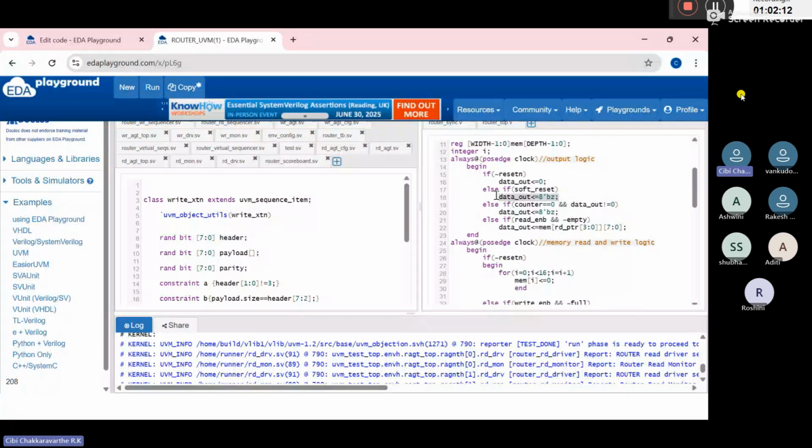If we are sending a packet to the destination and for a particular period of time there is no response from the destination side, for example, in some cases it is 30 clock cycles, then for around 30 clock cycles, if there is no response from the destination side, it will automatically do the soft reset. Soft reset in the sense it will not make the data 0. Instead, all the data will be moved to high impedance state. That is, it will be stopped. Everything will be stopped, and the bus process will not act there. The bus will not be in control at that time.